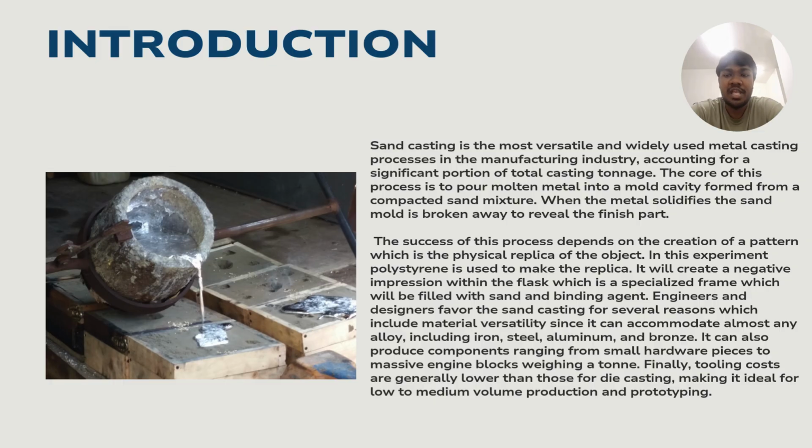Engineers and designers favor sand casting for several reasons, which include material versatility, so it can accommodate almost any alloy, including iron, steel, aluminum, and bronze. It can also produce components ranging from small hardware pieces to massive engine blocks weighing a ton. Finally, tooling costs are generally lower than those for die casting, making it ideal for low to medium volume production and prototyping.